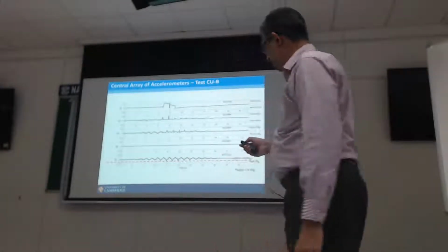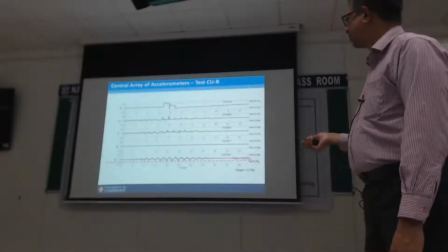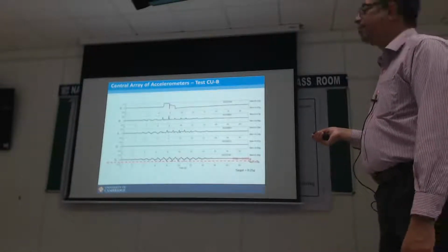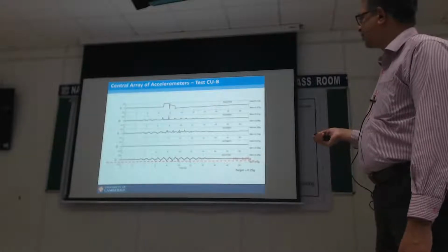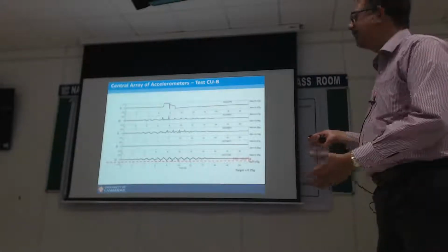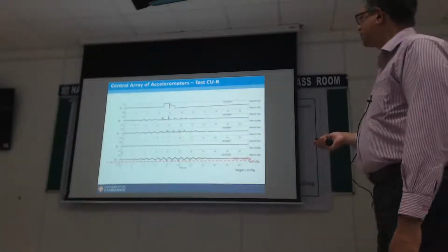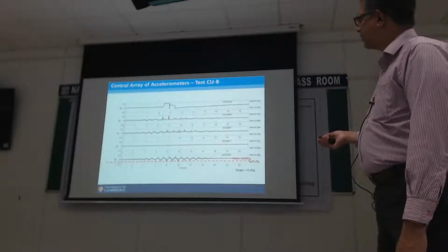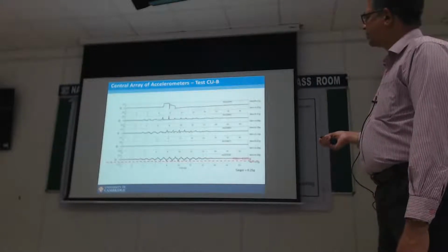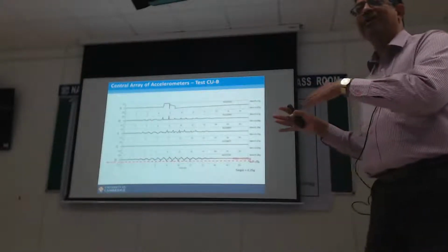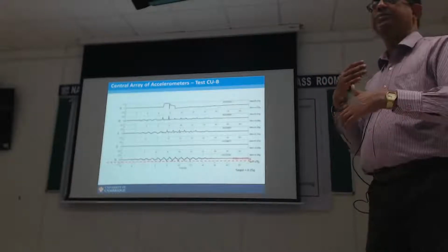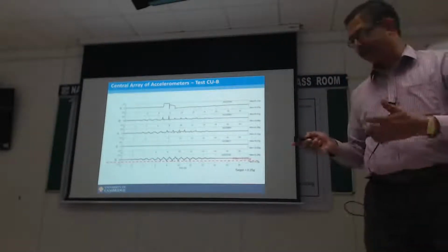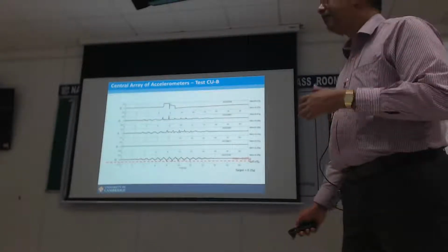But as I said, a few of our instruments did not work. That one did not work. Initially, I thought that also did not work, but actually, it turns out there's quite a bit of dilation going on at the top, so it could be trying to tell us something. But these two certainly work, and you can see that every half cycle or so the soil is stopping from moving. That's why we're getting big acceleration spikes, which we looked at yesterday. The new marketing explains all that quite well.